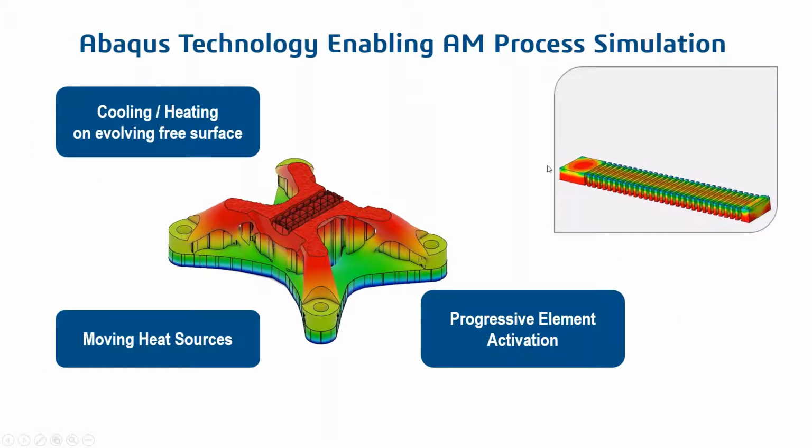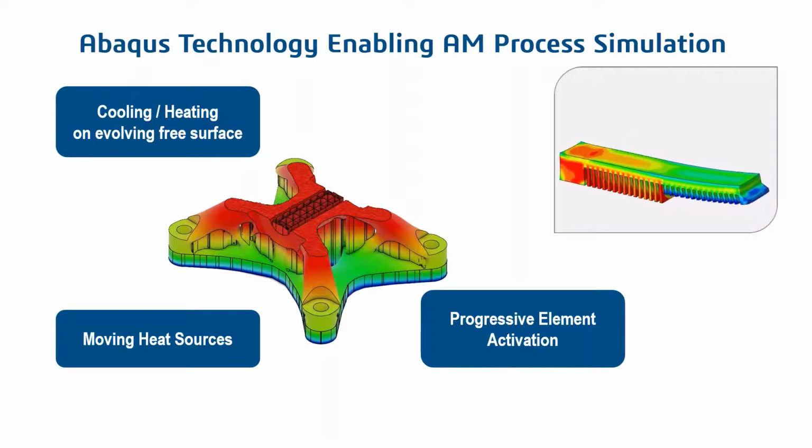Some technology we have recently been developing in the solvers has been with the purpose of providing simulation for additive manufacturing. To support simulation of this kind of manufacturing process, we need to be able to continuously add material to our simulation domain. So elements can be progressively activated, and during that process we can calculate what the free surfaces are to provide the correct cooling.